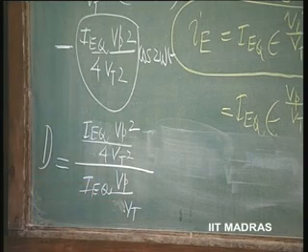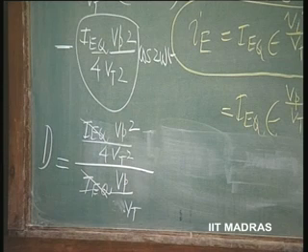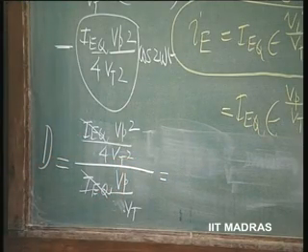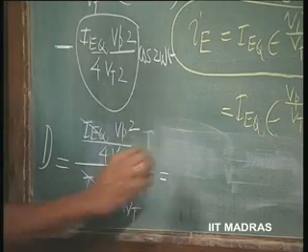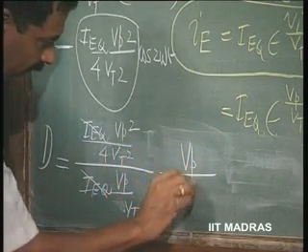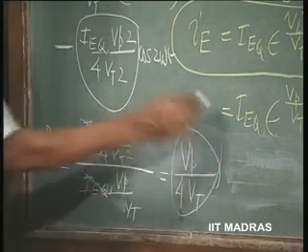Vt. So, how much is this? IEQ gets cancelled. So, it looks that the distortion factor is fairly independent of what? The operating point, right. So, we see here IEQ getting cancelled and it is equal to Vp divided by 4 Vt. It is an important thing.